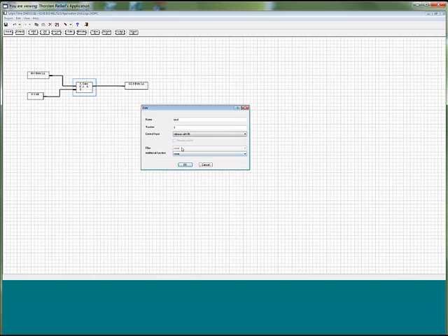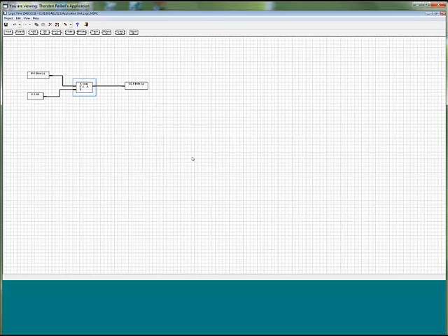We can use no filter. Filter is only possible when we have 1-bit information on our input and output. But here, for example, we can use save during blocking phase or with sender trigger. No additional function. And the last step is we have to link group addresses. Right mouse click, link to group addresses.